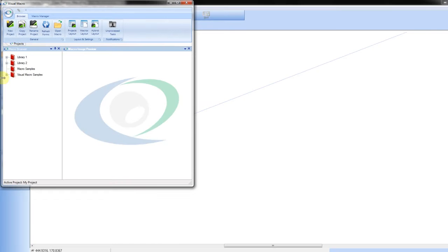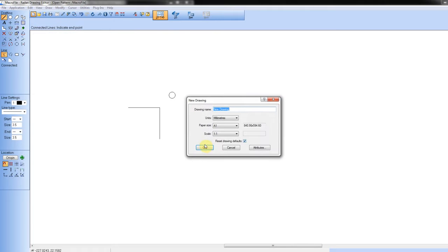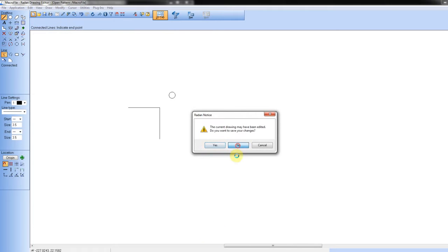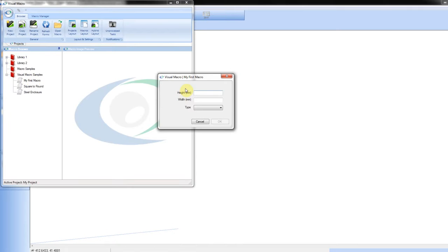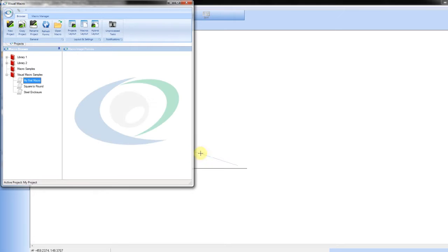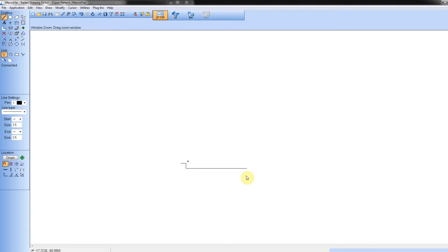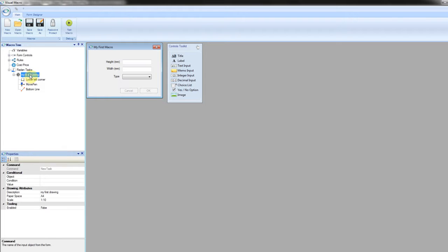For our example we will leave these properties at their defaults. OK, save the macro and close the workbench, and if there is a Radan drawing open, start a new drawing. Open your macro and enter some valid answers and click OK. Your Radan drawing should look something like this. OK, close the drawing and return to the macro in the workbench environment.